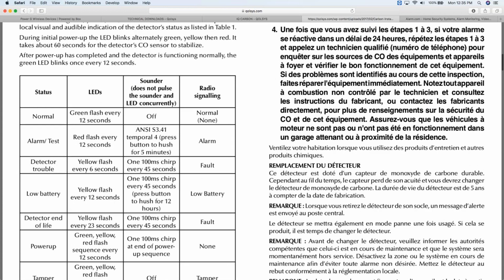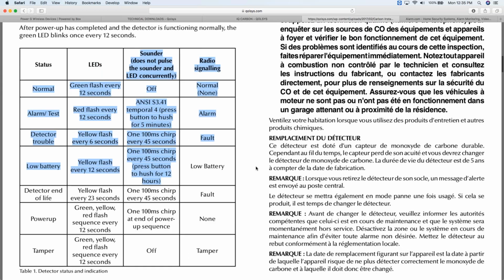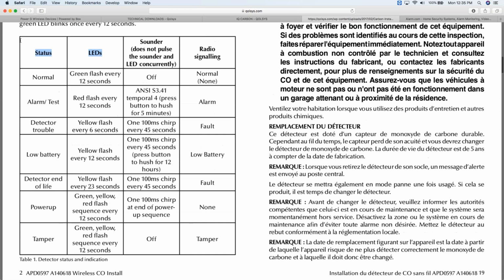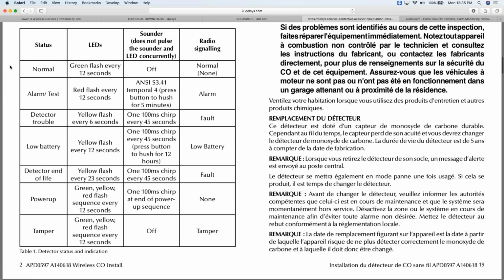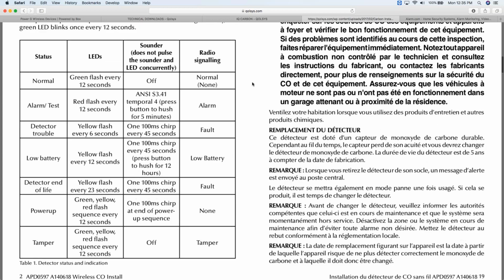This thing. Both our smoke detectors and carbon monoxide detectors have these guides, or I guess these manuals, in the box with the sensor, right? As technicians, if something goes wrong with your carbon monoxide detector or smoke detector and it's faulty, we just want to swap it. But a lot of times, if that thing is chirping or beeping, it doesn't necessarily mean it's got a low battery or that it's not working. It could mean something else.